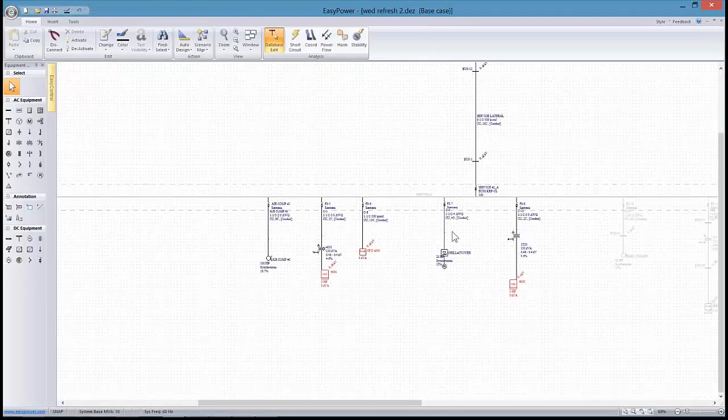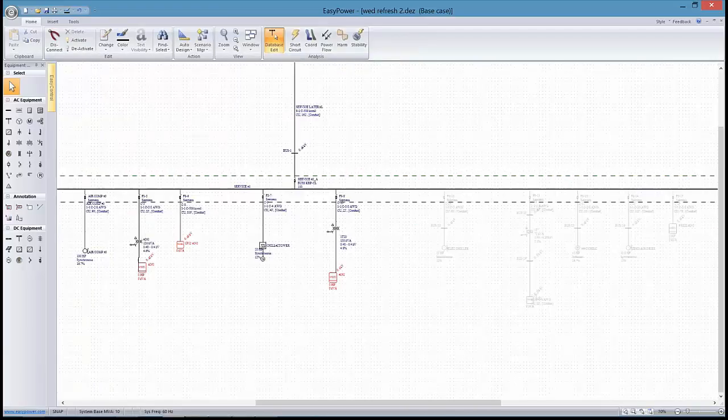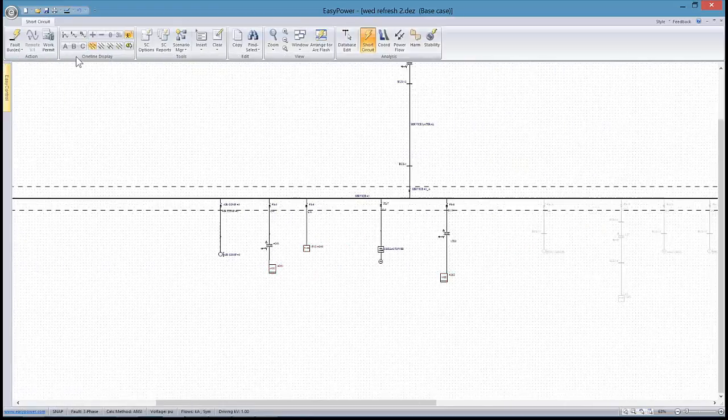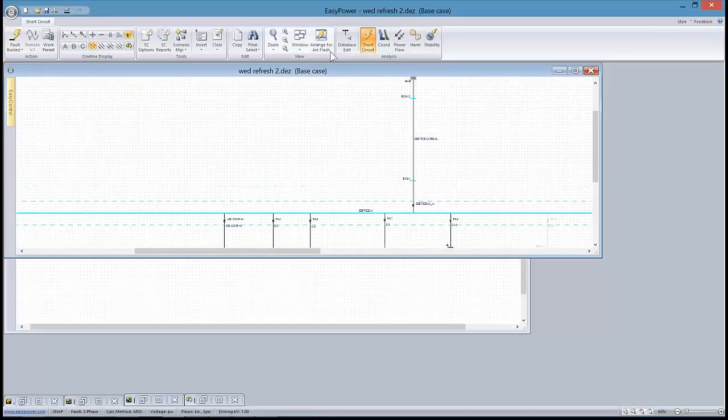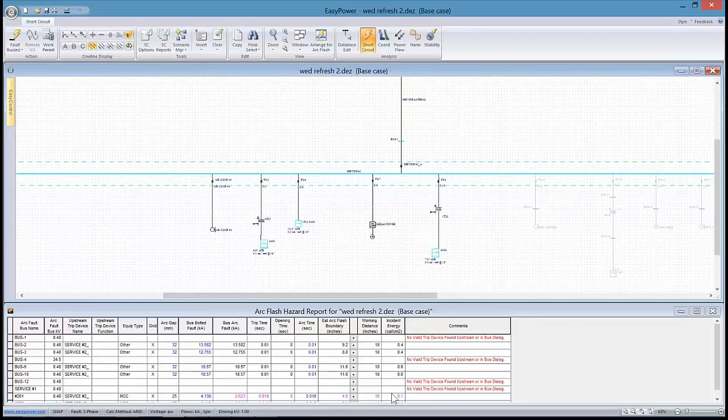So again, what this shows is that I've deactivated this particular bus. So by activating that and still have the loads deactivated, we should be able to go back online. All right, so now we're faulting the bus, and now we're seeing results, calculations, and likewise, we're seeing some elements that still aren't connected or don't see a trip device. So far and away, this is the most frequently seen beginner's mistake, and that is you haven't fully characterized a protective trip device.